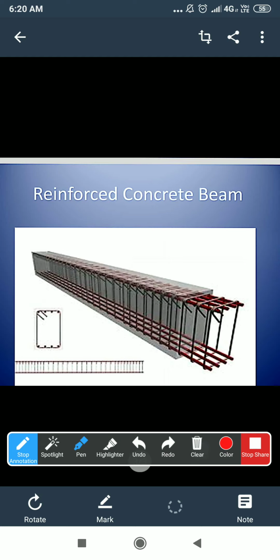Okay, now next we shall consider a small example of drawing a simply supported beam which consists of four bars in the tension face, four bars in the compression face, and two-legged vertical stirrups. The stirrups have the usual spacing, a common spacing from start to end. I'm taking this example in order to help you understand how the reinforcement will begin. So here I'm taking the example of a simply supported beam.